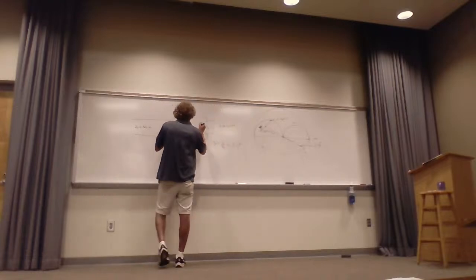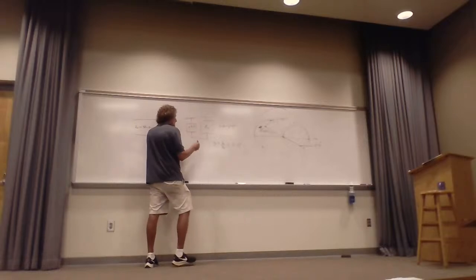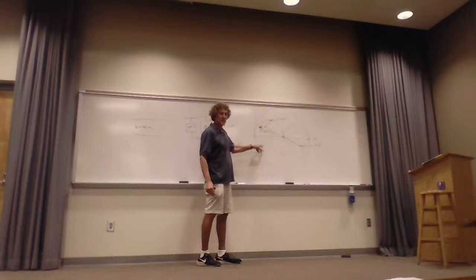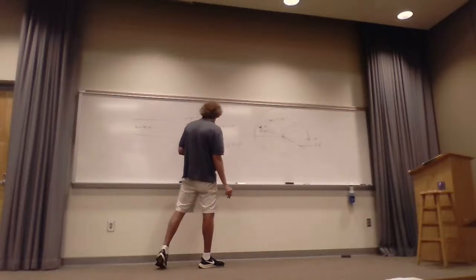So now I'm going to say I have a normalized admittance here of j0.2. I could have gone down here too to 0.1 minus j0.3, but I'm adding a positive j because I want a capacitor. Okay? And I'll show you how to calculate the value in a second.